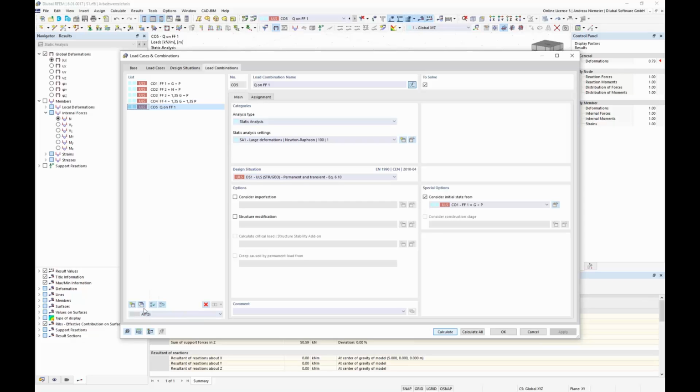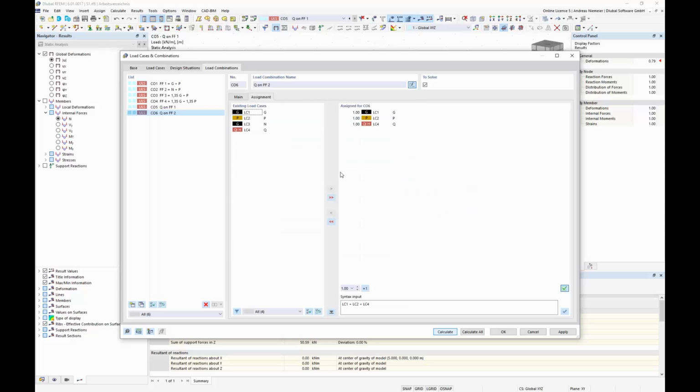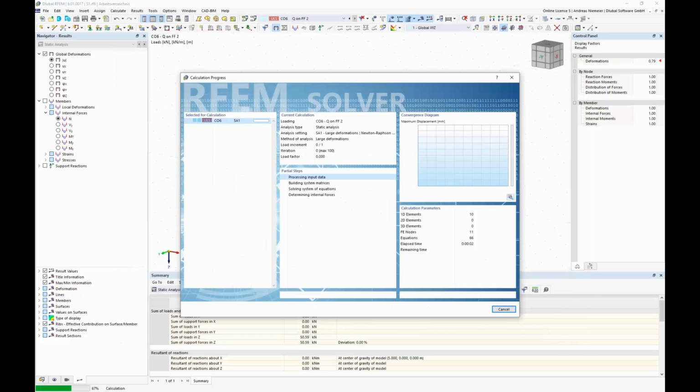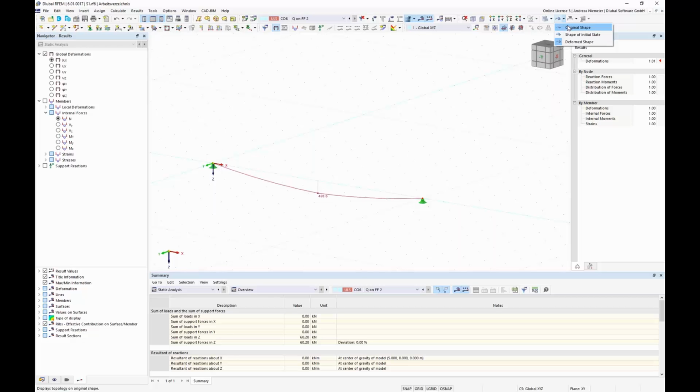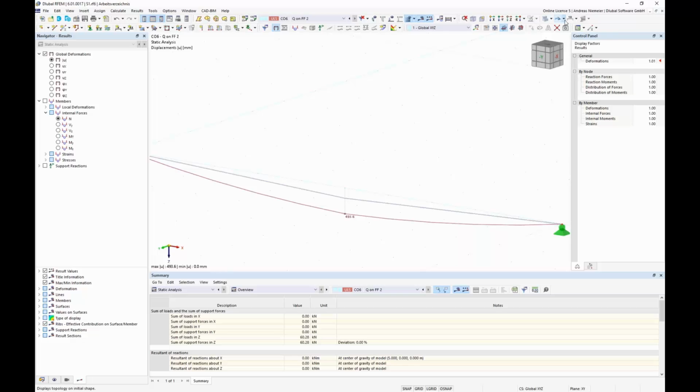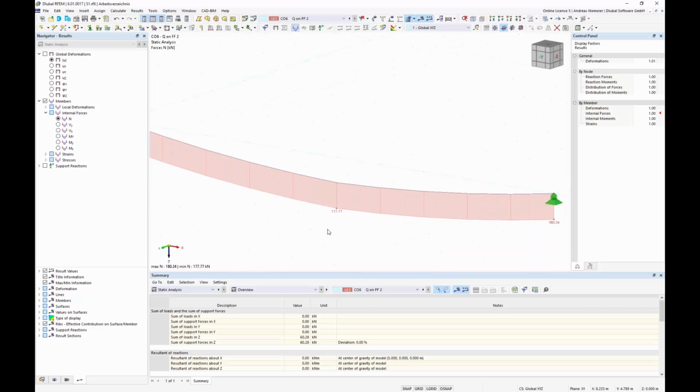and if you wish, you can also apply the same load on shape 2, which means we only change here to shape 2 and exchange the load to N. And with the calculation we get the same task, only on, let's say, original form finding shape 2 plus load is on deformed shape with 493 millimeters with a normal axial force of 177.